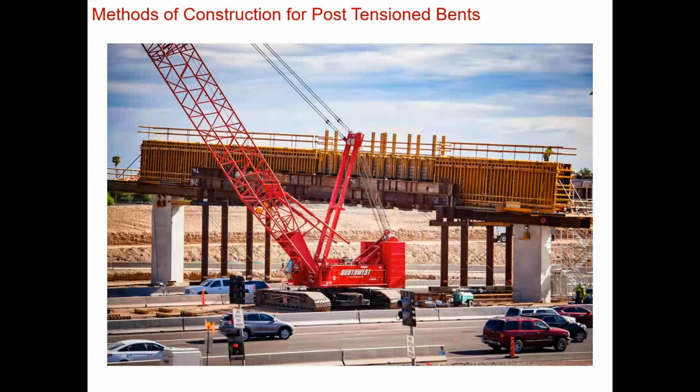This is just showing an example of this type of construction where you have the false work set here crossing or straddling the roadway, and you have the steel shoring towers here, supporting the formwork where you're going to cast your bent and post-tension it in the air, basically. So that's the type of construction that uses the false work.